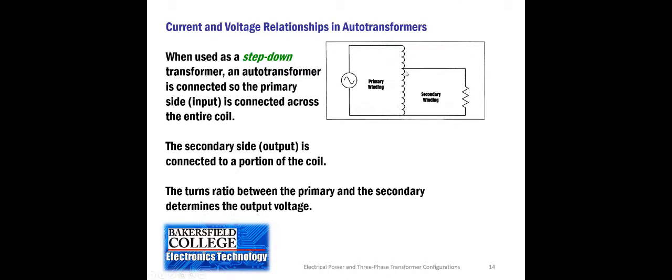This is like having a couple of resistors in series with each other. Let's say you have one resistor that is 3,000 ohms, and then another resistor that's 1,000 ohms. The voltage will divide across the total resistance proportional to the resistance value. So the 3K is going to have 3/4 of the voltage across it. The 1K will have 1/4 of the total voltage across it.